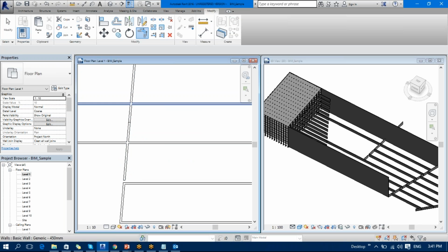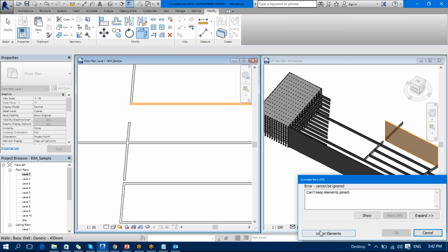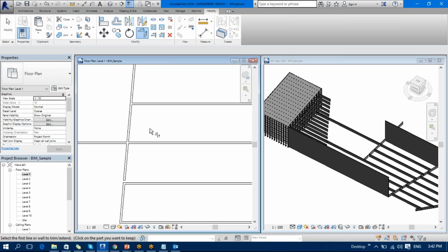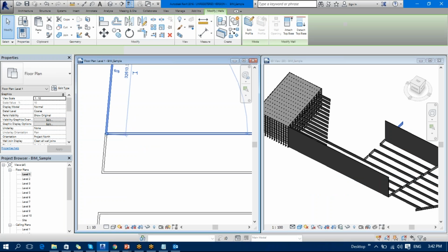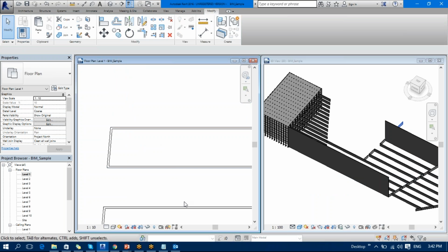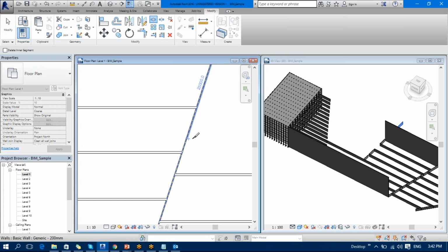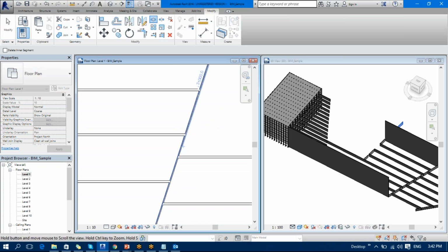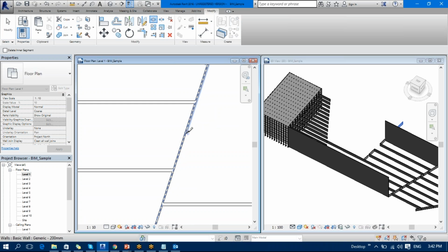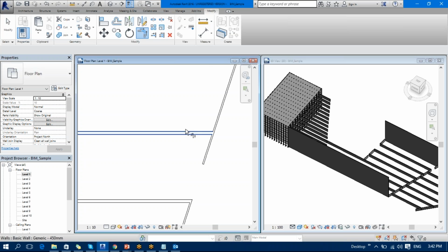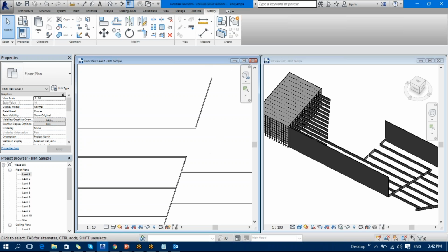Now over here I just say trim, join, and I say SL, I select this part or supposedly this part, and I say trim. No need to delete afterwards, just select a single time. So it depends upon how you use this split command.